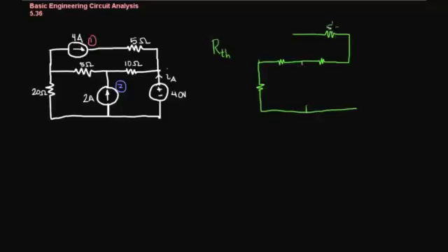that's what our circuit looks like with all of the sources removed. And again, remember that we're calculating the resistance across our open terminals here. So when you look at this, you'll see that the 5 ohm resistor at the top contributes nothing, and that the rest of the resistors are in series. And so our R Thevenin is simply 35 ohms.